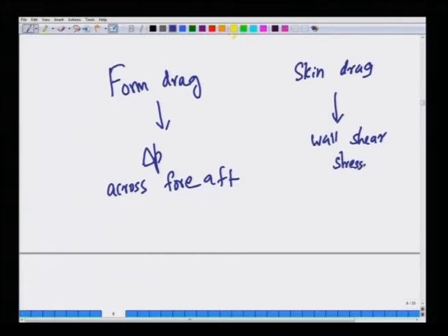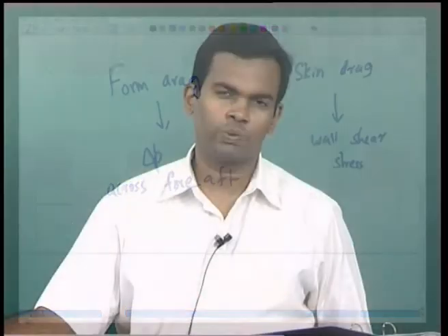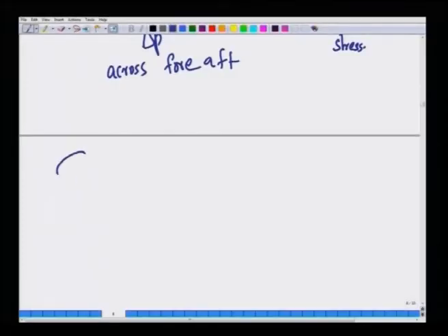Now, therefore, in order to calculate the drag on objects such as spheres or cylinders, it is not just possible to do theory or analysis alone. You have to do experiments, and if you remember, we did dimensional analysis, which tells the drag force in terms of a non-dimensional drag coefficient, which is nothing but the drag force F divided by half rho v squared d squared, where d is the diameter of a sphere.